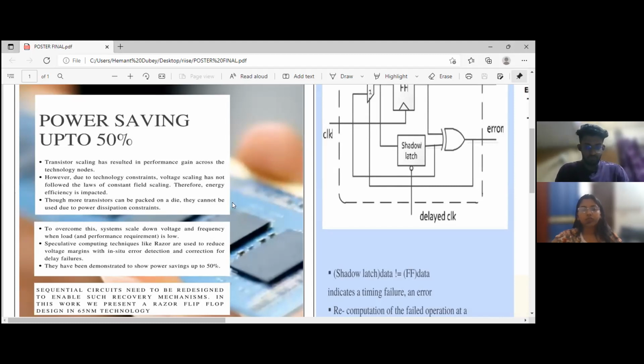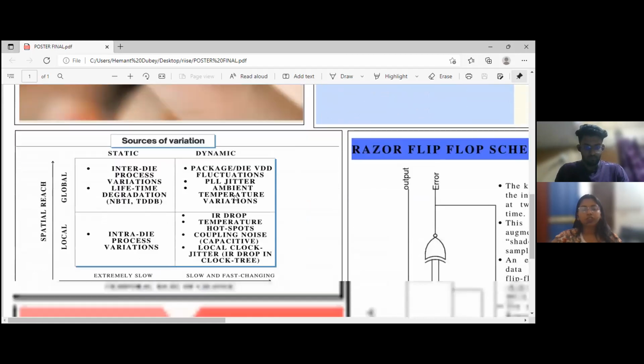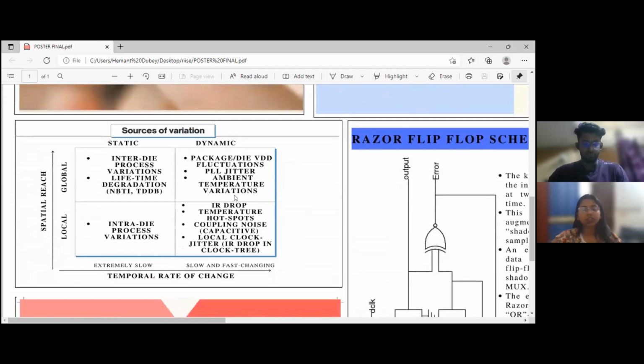Power consumption issues are further increased by variation in transistor performance at aggressive geometries. The sources of variation can be global or local in extent, or static or dynamic in nature. While the practice of adding a safety margin or guard band to supply voltage leads to robust circuit operation in presence of variations, it also leads to higher power consumption.